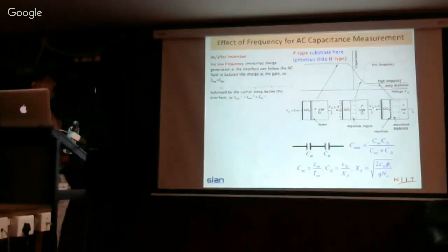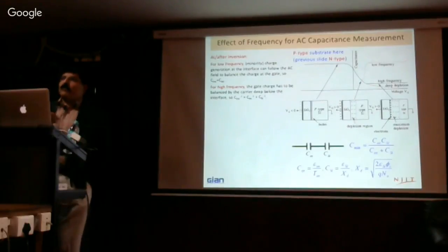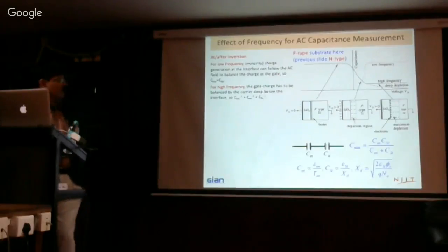Now in high frequency, you cannot follow the generation of carriers that is coming from the substrate, it cannot follow the high frequency. That's why this capacitance doesn't change.